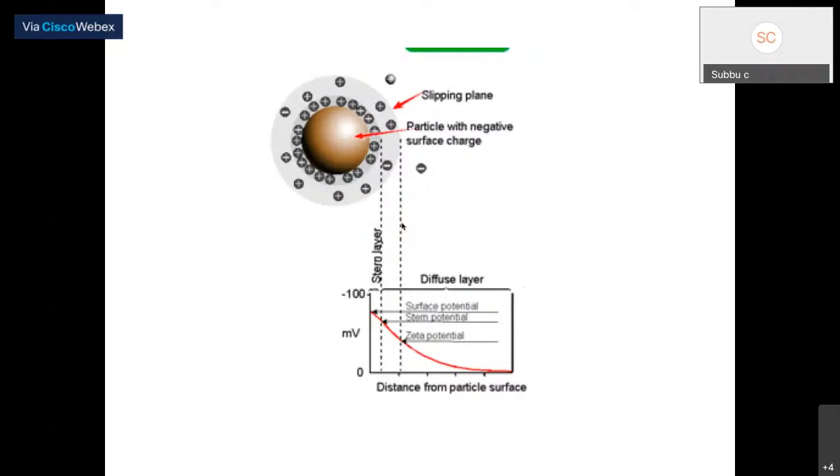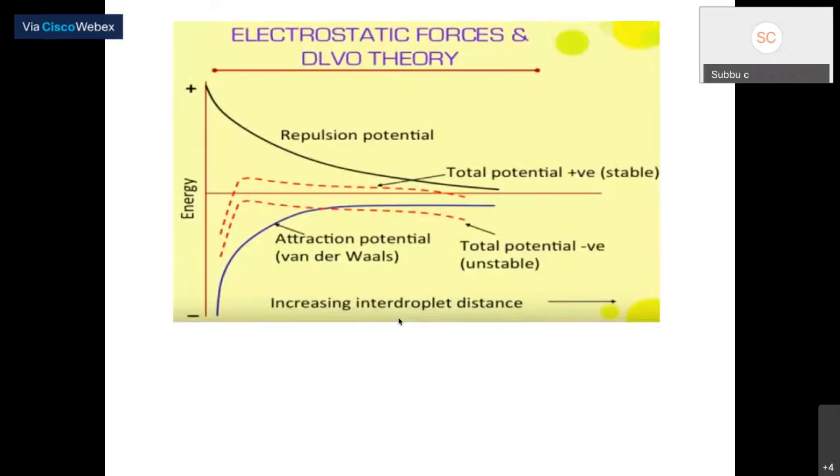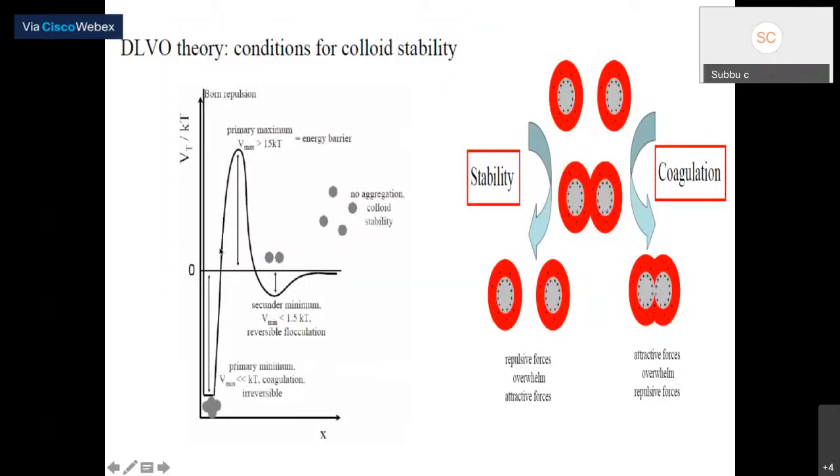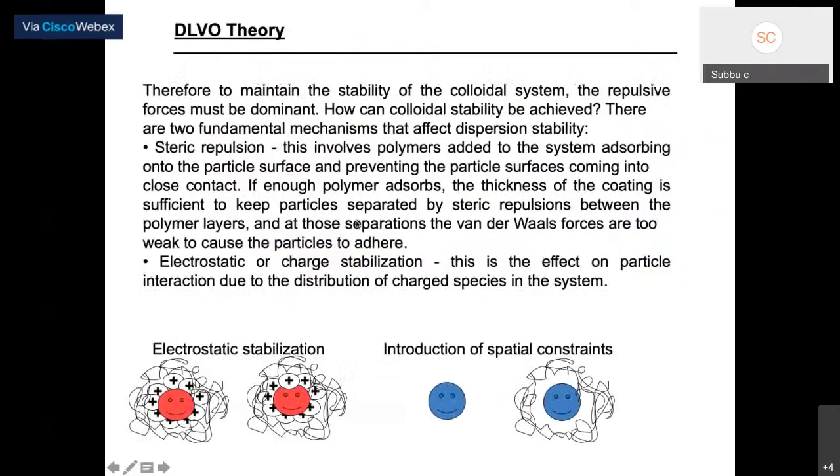If I maintain that minimum pH, I will be in a position to control the medium. That means the attraction and repulsion forces you are playing with by varying the pH of the medium. So your net force can be controlled in such a way that you don't want it to coagulate or flocculate, so there is no aggregation, nothing. So always ensure you maintain that pH. That is the way to stabilize a colloidal particle.